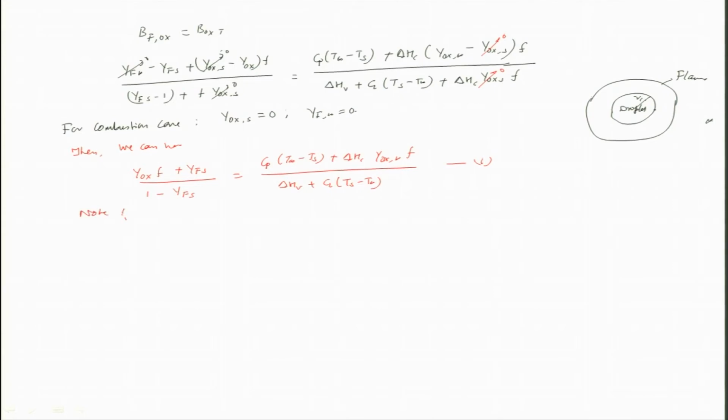Note that Y_F,S and Ts are unknown, but Y_F can be related to partial pressure Pf. So, Y_F we know is nothing but rho F by rho, which is nothing but Pf by P times molecular weight of fuel divided by molecular weight of mixture, right.